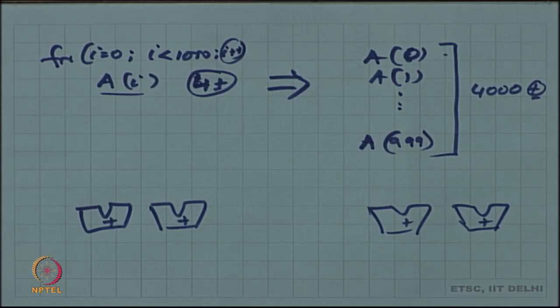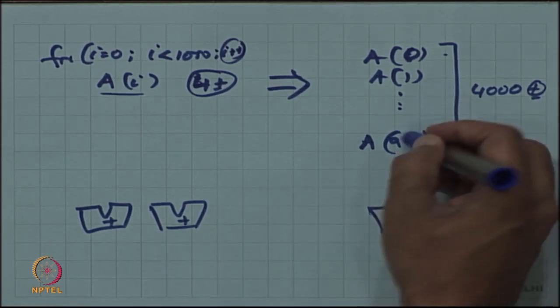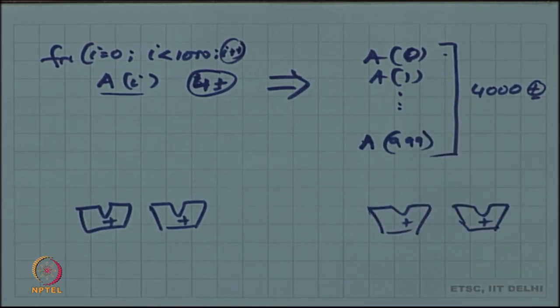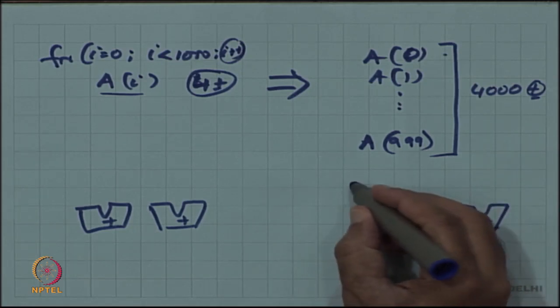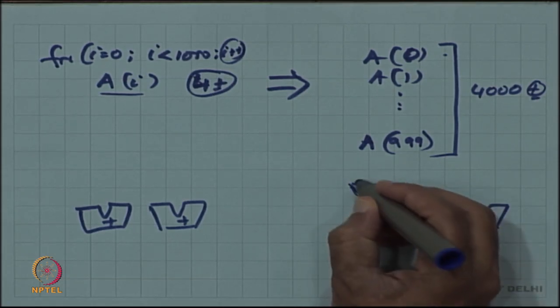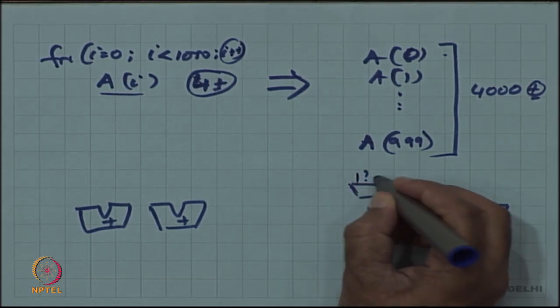Okay. What else is the other implication? We want to compare ultimately the 2 circuits that are the outputs of the synthesis and possibly make a decision on which is better. I said 1000, but you can extend it to large numbers and see if you can predict an impact. Multiplexers will be required in the second one. If you need a mux here, what is the width of this mux?